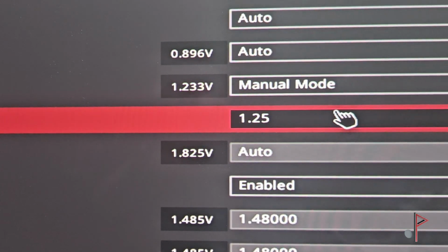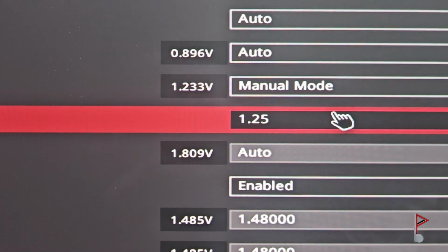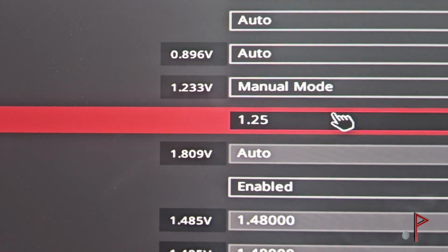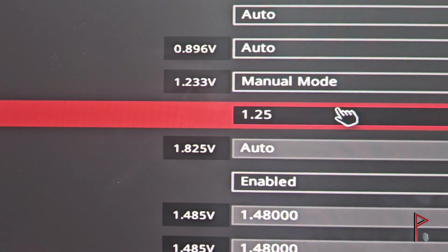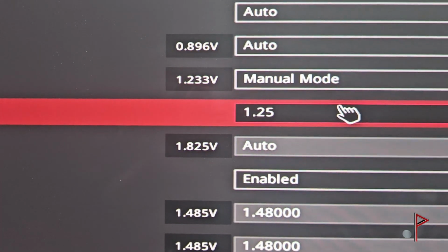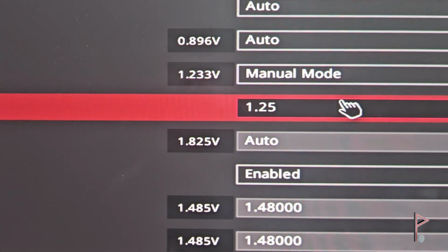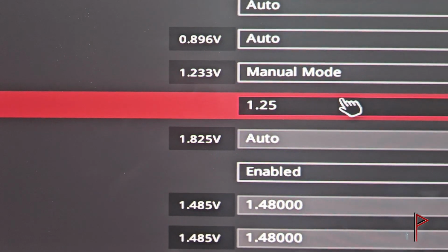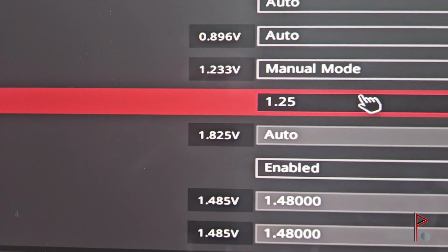So you might be overclocking, tuning, and although it might seem counterintuitive, pumping more voltage into this might actually hurt your performance. So when you find that, you maybe go down to 1.2, and then you might adjust from there to 1.21 or maybe 1.18 or something like that. You might have to go lower to achieve the desired result. So that's system agent.